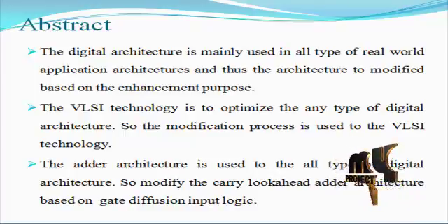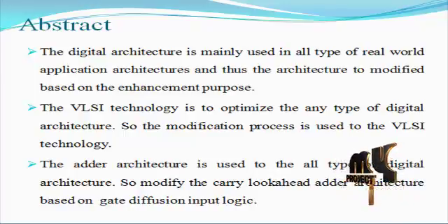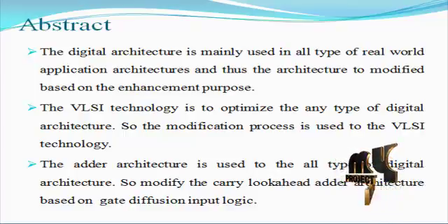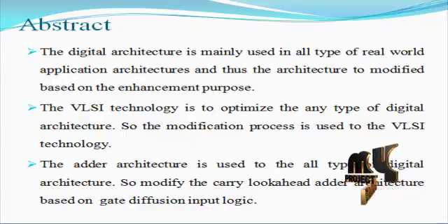The common blocks of the 8-bit multiplier in both GDI and CMOS designs are the Booth encoder, compiled for efficient generation of partial products. The partial products are either multiplicand or multiplier operations, depending on the output of the Booth encoder. The Wallace tree technique implements full adder based architectures to reduce the addition architecture results and implement the partial product generation unit.